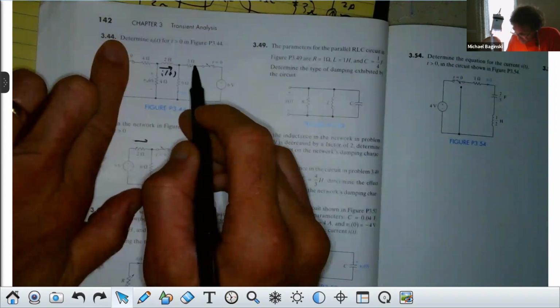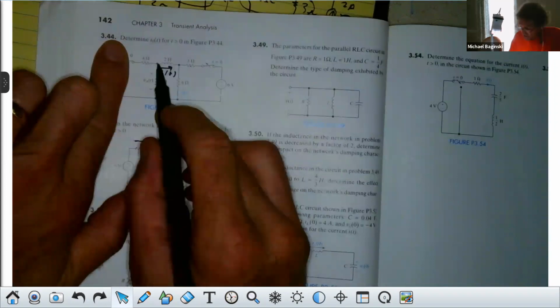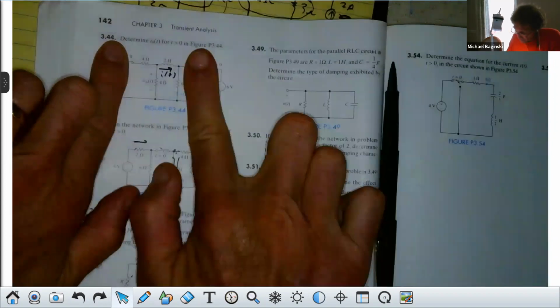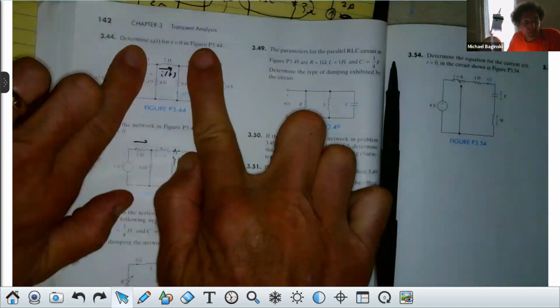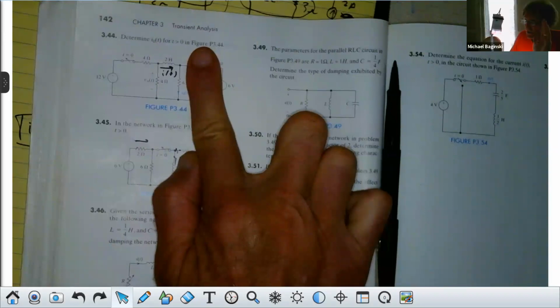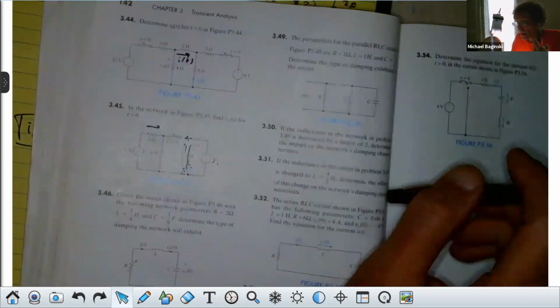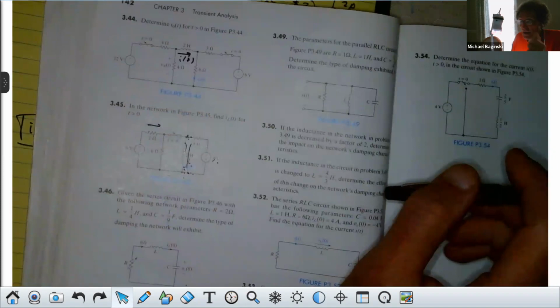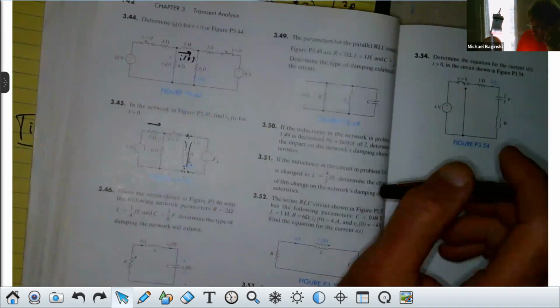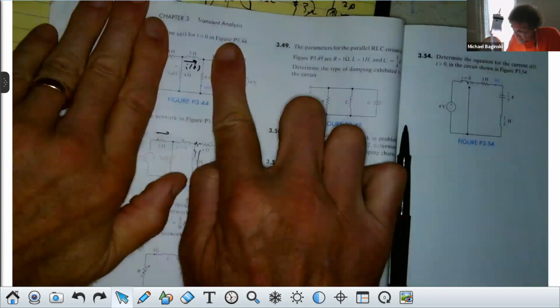The only thing that's going to have a bearing are the 6 and the 4, correct? So what would R Thevenin be when this inductor is taken out? Remember, that's not there, that's not there. What would R Thevenin be, class? 10 ohms. How many see it's 10 ohms? I'm really trying my best to get this across. Now, once you have that, we have tau, don't we? If we've got R Thevenin, we better have tau, right? It's L over R. Now that we have that, back to t greater than 0. That's the circuit for t greater than 0.